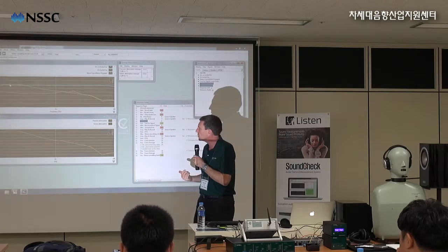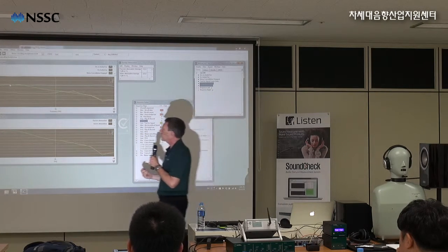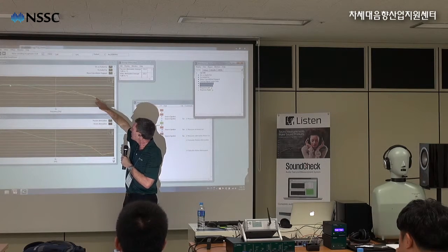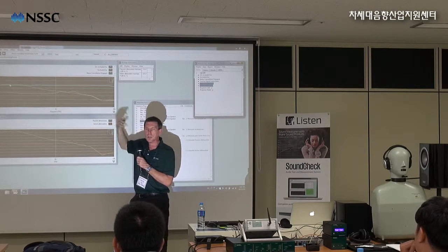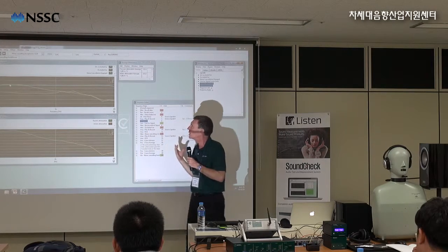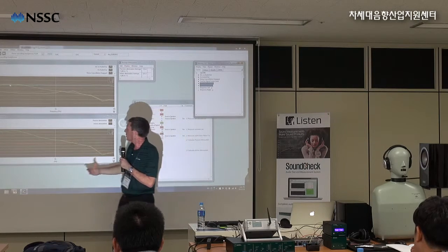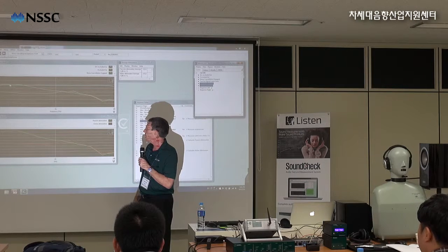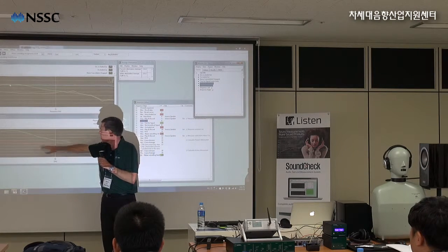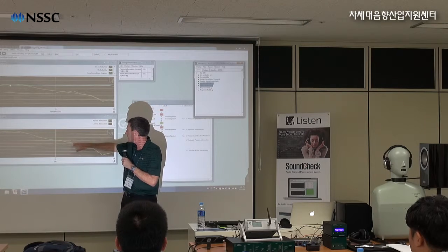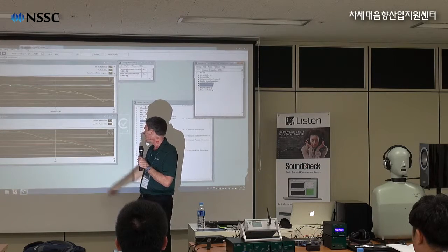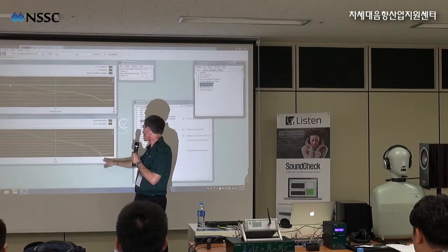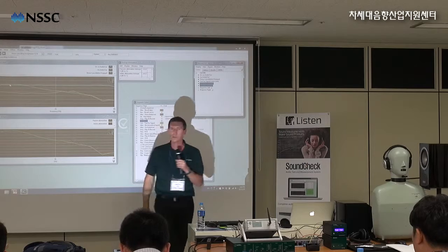So if you look at the two together, you say, okay, this is my total. I got almost no difference at the high frequencies by turning the active noise cancellation circuit on. But if I combine the two, I'm actually getting this red curve here, which is my total attenuation. And I can get 20 dB at low frequencies, 15 dB at 2 kilohertz, and then at very high frequencies, about 5 kilohertz and up, I'm starting to get as much as 30 to 40 dB attenuation.